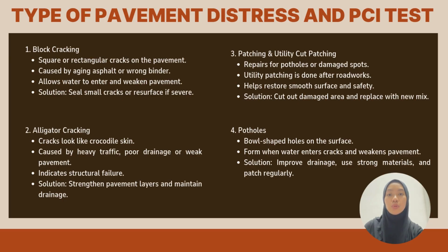So next is pothole. Potholes are round holes caused by water and traffic. Water weakens the pavement and the vehicles make it worse. So the fix includes patching and better drainage.